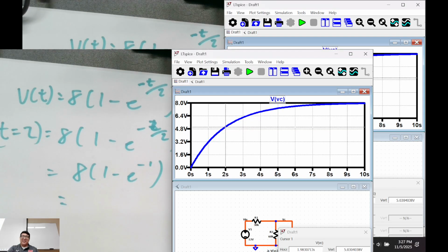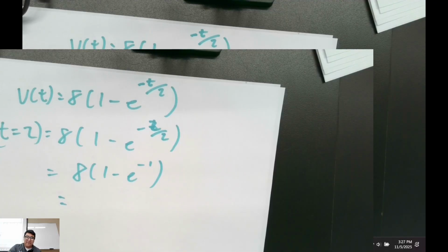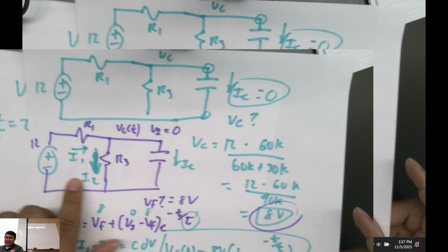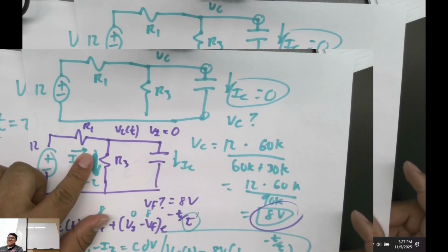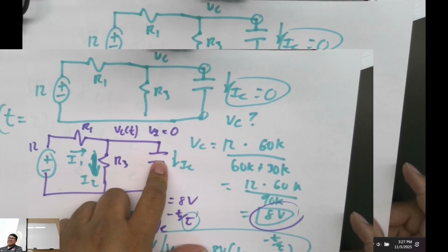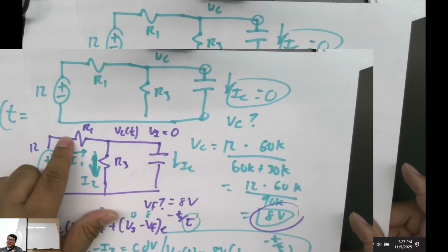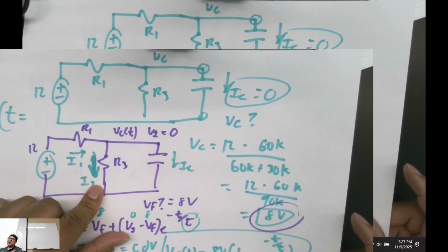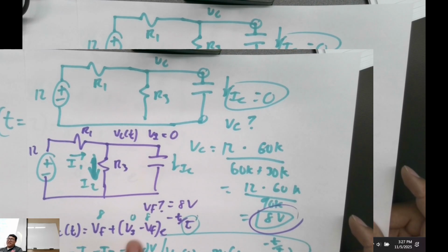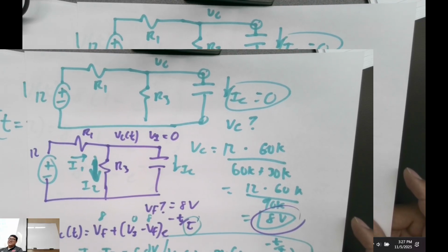So the reason why I was trying to show you guys the LTspice thing is because we were trying to figure out, okay, we have the condition where we have two resistors, right? But they're both being dominated by whatever the current in this capacitor is, right? IC is equal to the current in this one minus the current going out, right? So that means these two currents are directly playing with this differential, right?